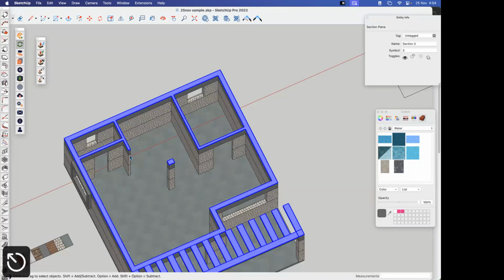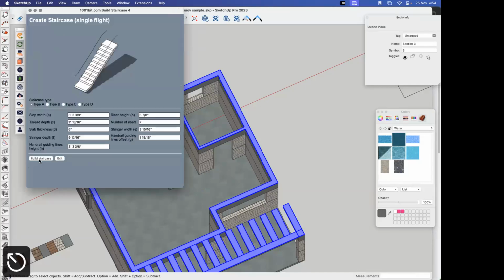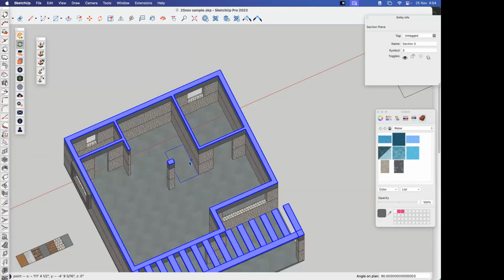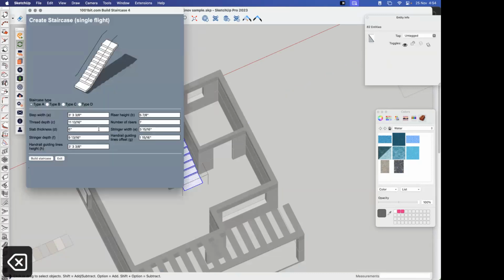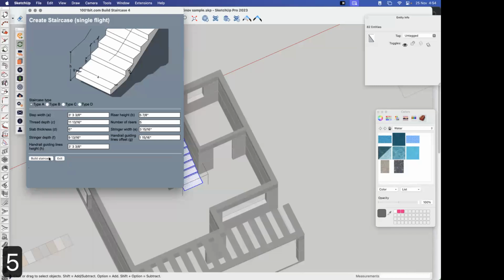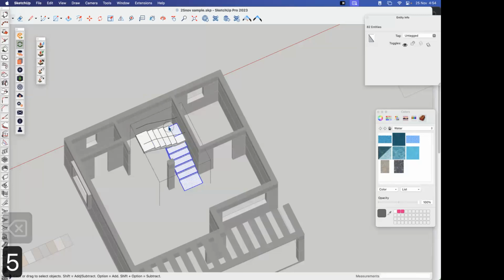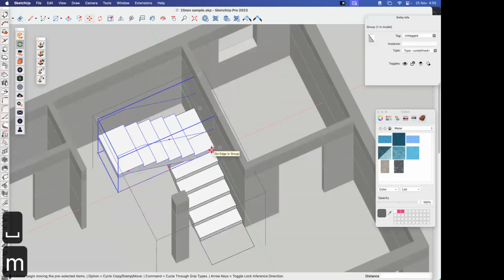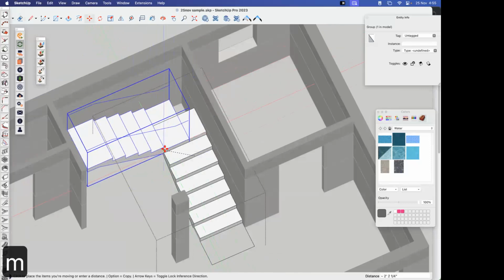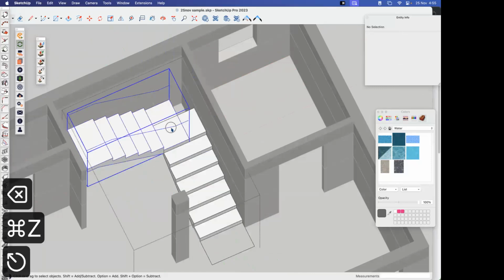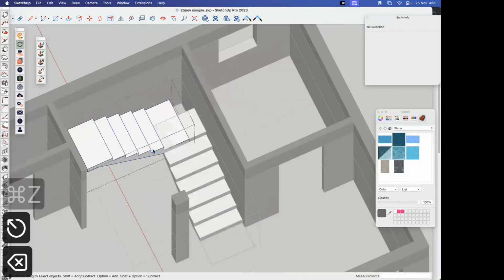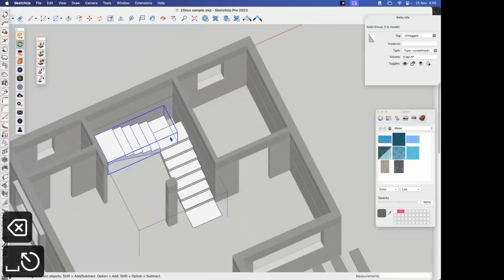So I'll just add the staircase quickly in the same file. Add the staircase module, create the staircase. Once I go inside, I create the railing. I take the staircase, use it again. Let's say I want it for 5, or yeah, 5 sounds right. I create one more line of staircase. Thus I can position it based on the previous staircase. And then I can create another on the